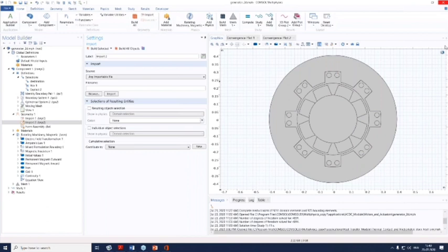The next question is what is the need of programming options in geometry. With geometry programming, you can implement some programming. For example, if you have certain parameters defined in your geometry, and you want to say that if a certain parameter value is set equal to 2, then execute a part of that code, and if that parameter value is given as 1, then execute another part of the code. In those cases, this programming can be useful.